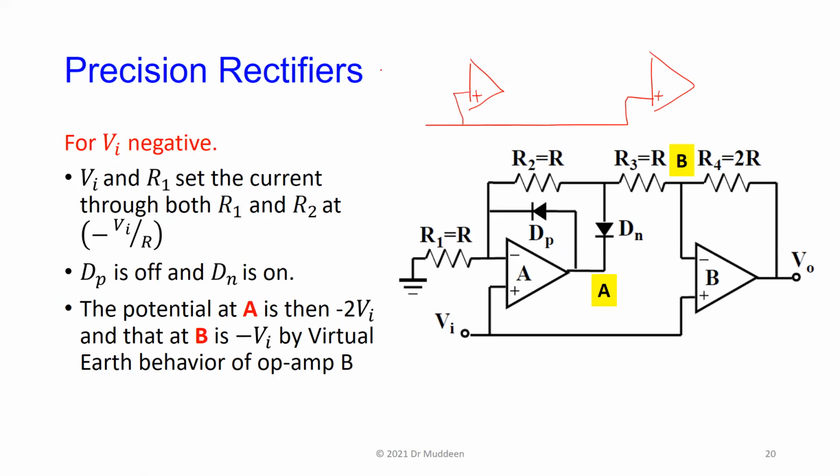Right, we have ground, we have one resistor, two resistors, three resistors coming on the output here, connected here, and here is connected here, right? So we have V in here, right? So that is what it is when Vn is negative. Forget the diodes. This is the behavior now. Because Vn is negative, this diode is now biased.